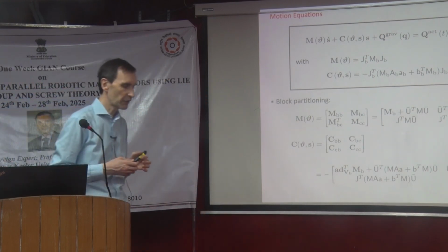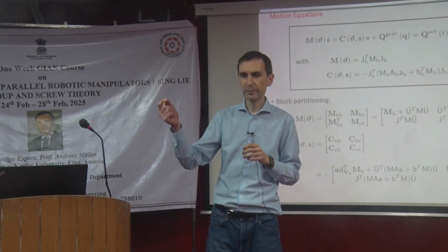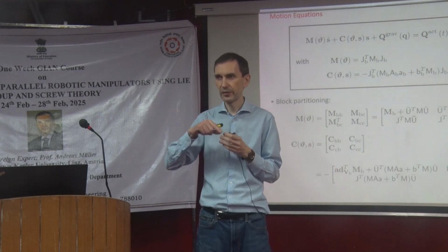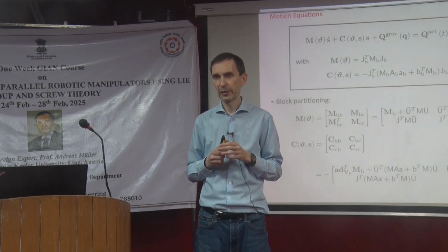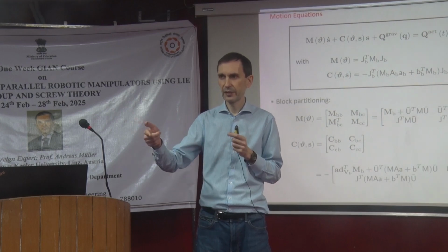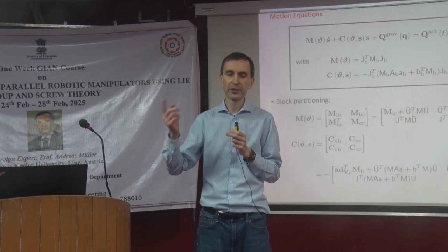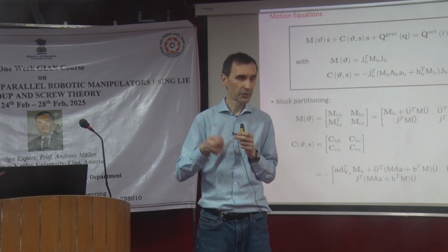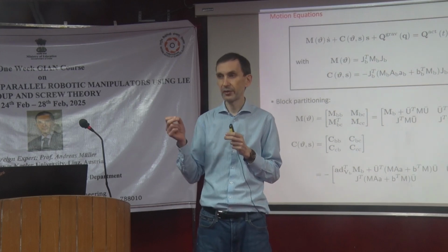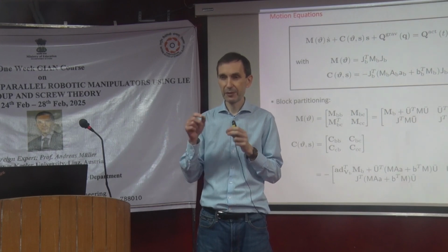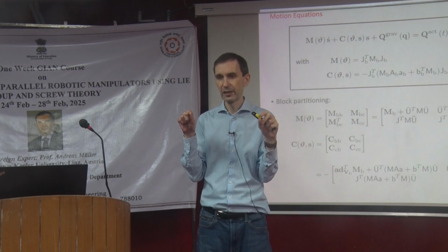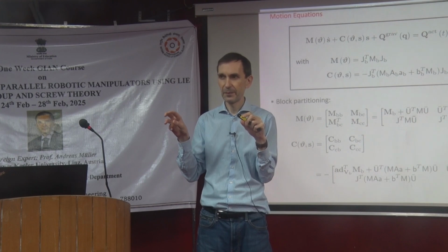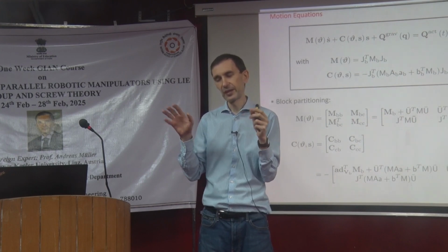There are many things to consider, because if you just use random sine functions, for example, or a chirp function, where you increase the frequency, you have to be very careful, because then you are exciting nonlinear effects, and this is not what you want. That's why they use what's called odd random phase sine functions. So you have a sine function with a certain frequency, plus a phase offset, and the phase is random.